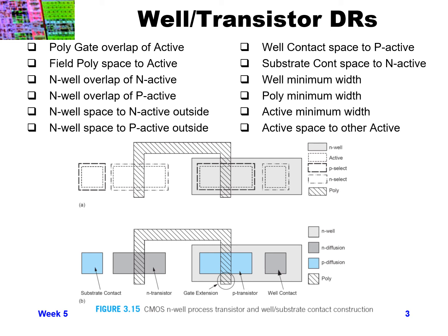Highly doped N and P, a reverse bias PN region with really high doping concentration, will also have a lower breakdown voltage, and so that's a problem. So you don't want those spaced too closely together. Any substrate contact has to be spaced out from your N active.